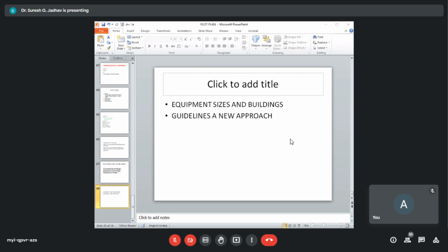Now, the next type of structure mounted arrangement is the vertical arrangement. The structure mounted vertical arrangement has equipment located at multiple levels in steel or concrete structures. This could be indoor or outdoor. The advantages are a small amount of ground coverage and the ability to house the facility to suit process requirements or climate conditions.